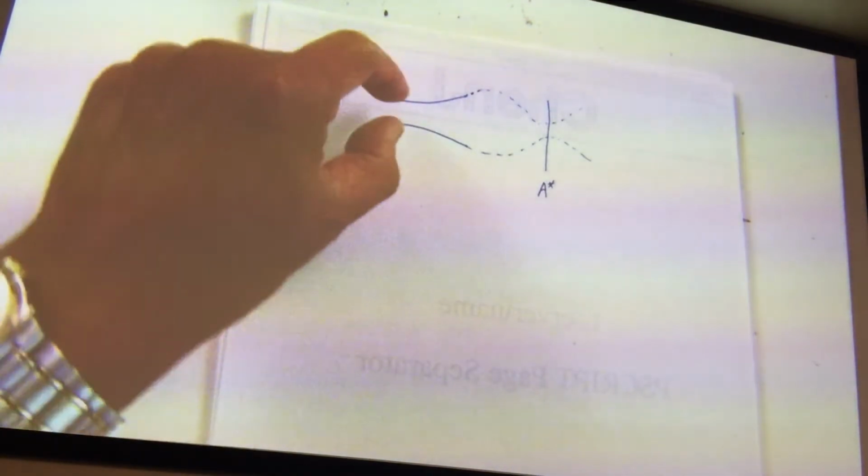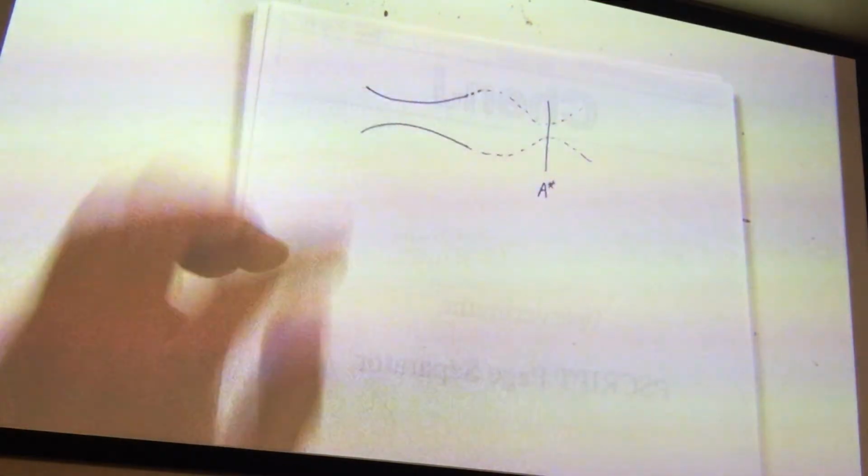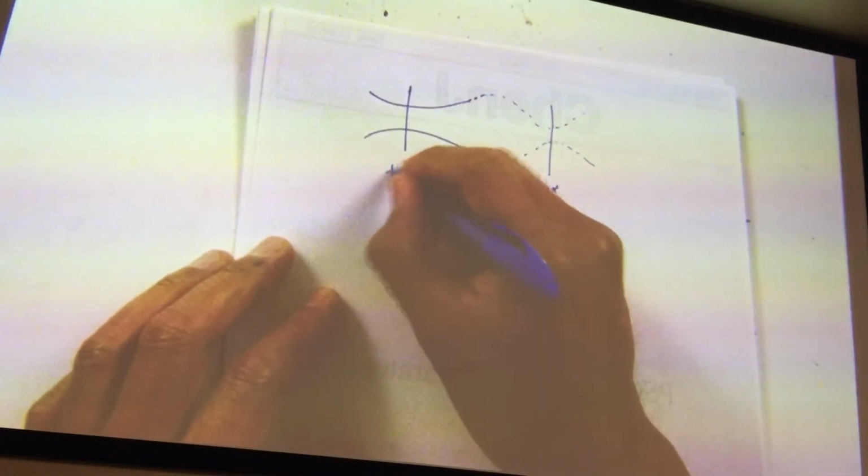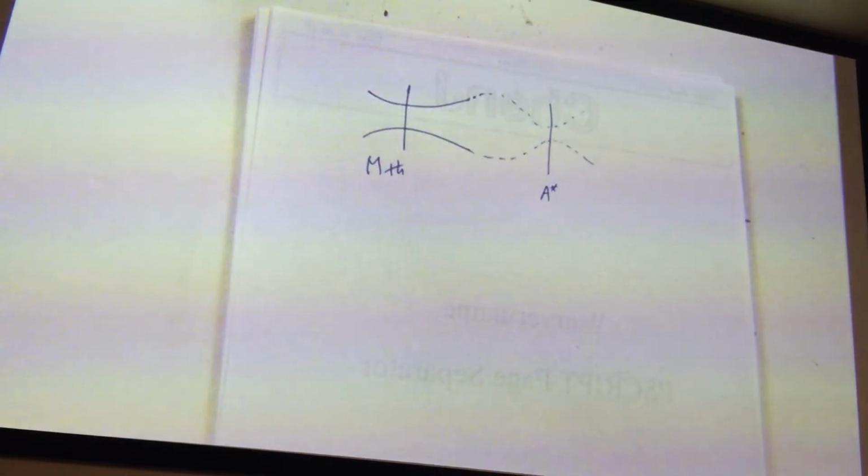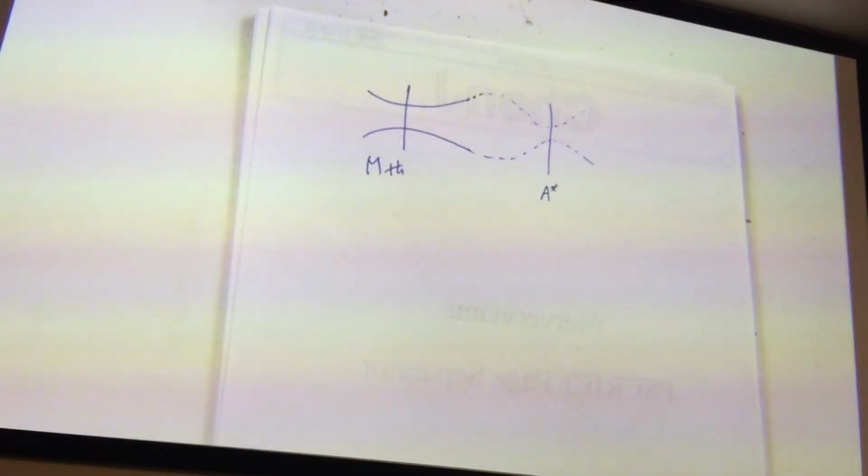And you take the ratio between these two, then you would know your Mach number in the throat. The throat condition is not necessarily sonic condition, but if you have sufficiently high pressure, then your throat condition is sonic condition. So your M throat is equal to 1, and your A throat will be equal to A star. But in general, your A throat is just A throat, right? The A star will be somewhere in your imagination, right?